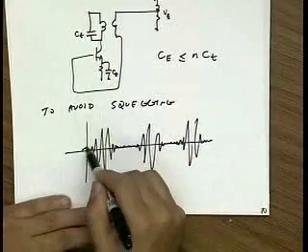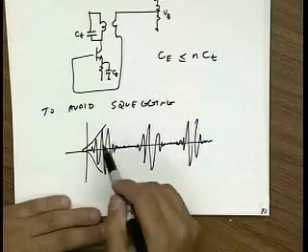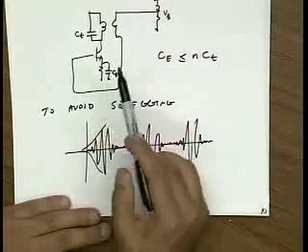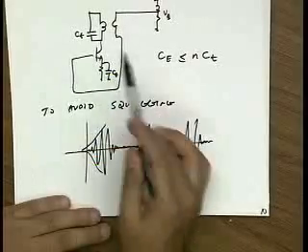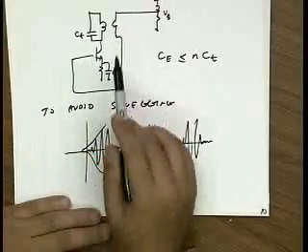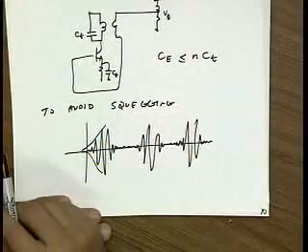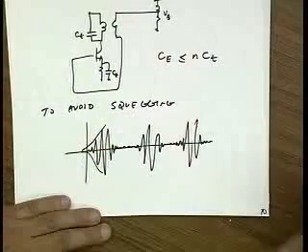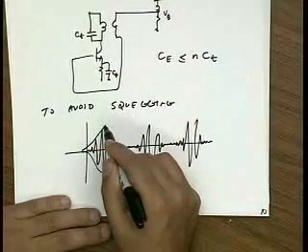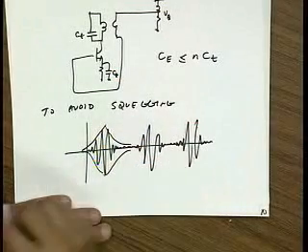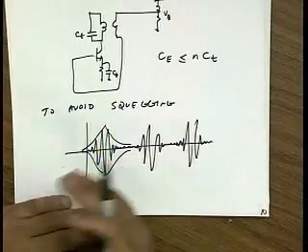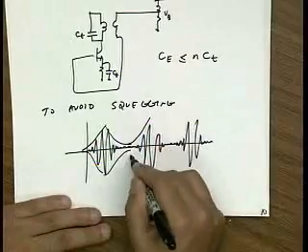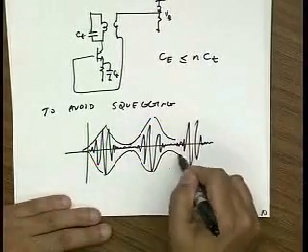In other words, the amplitude grows, but because of the time constant of this bias circuit, the bias circuit is slowing the circuit too much down, and it can't go into steady state in time. And so before it's gone into steady state, the poles move back into the left half plane, and the oscillation dies. But as soon as it dies, the GM of the transistor gets bigger again, the poles move into the right half plane, and the amplitude comes alive again. And this keeps happening over and over again.